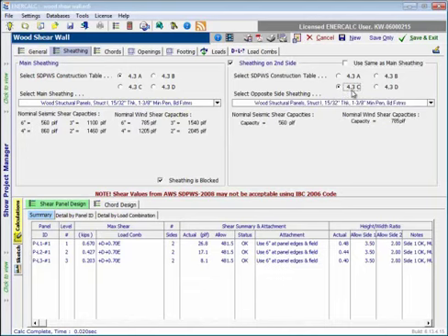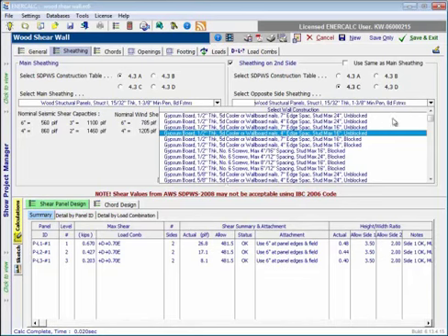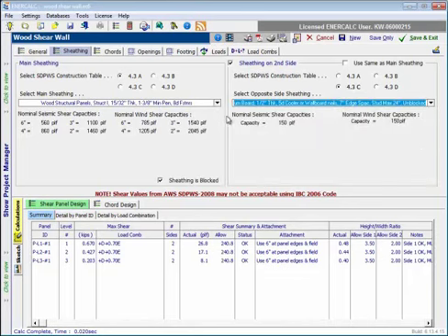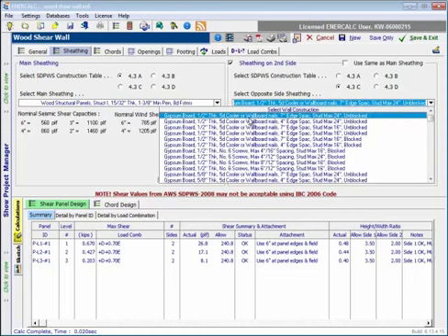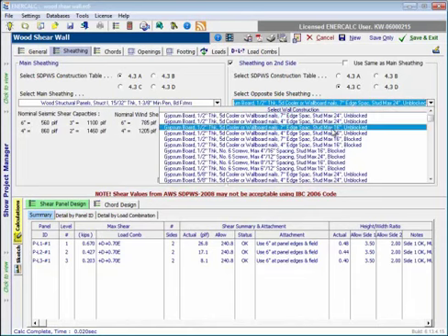So we'll come to table 4.3c, which defines the options for gypsum board walls. And then let's just choose this particular option here, and for convenience to read the whole description, that is 1/2-inch gypsum with 5-penny cooler nails at a 7-inch edge spacing. Stud maximum spacing is 24 inches. Just for convenience, let's come down to one that's 16-inch spacing.